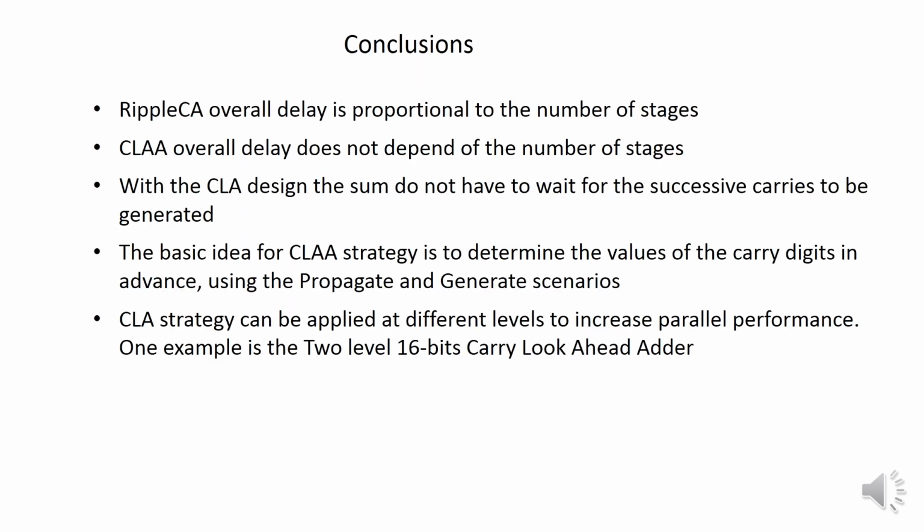In summary, the ripple carry adder overall delay is proportional to the number of stages, but the carry look ahead adder overall delay does not depend on the number of stages. With the carry look ahead adder design, the sum does not have to wait for the successive carries to be generated.